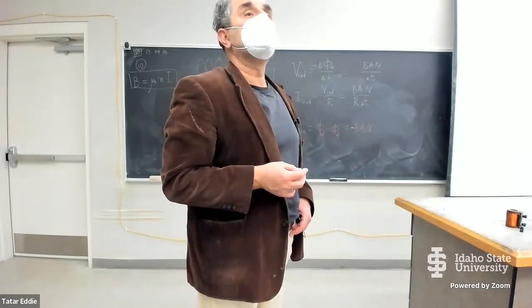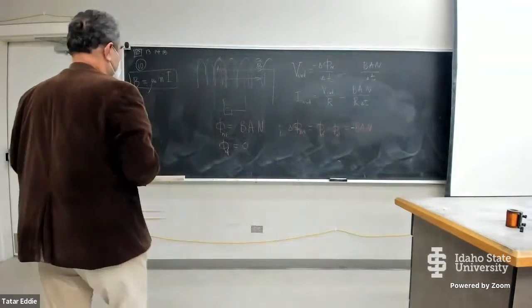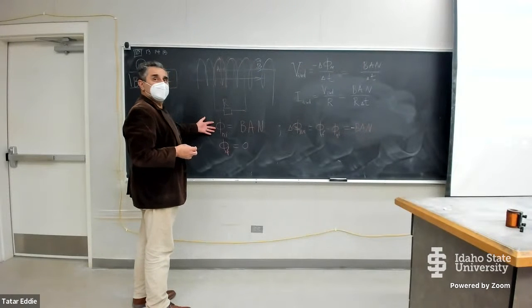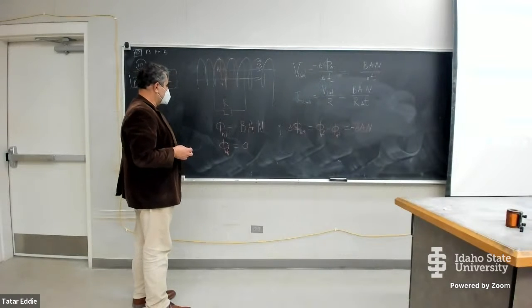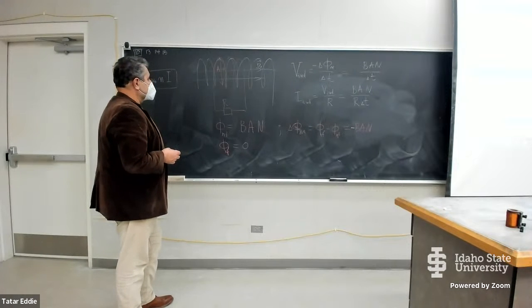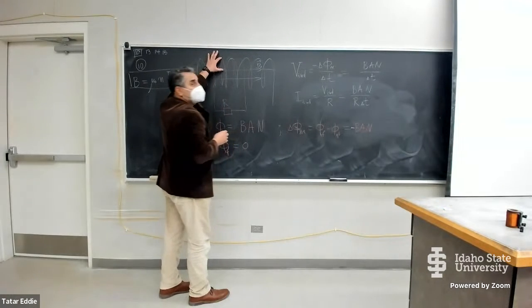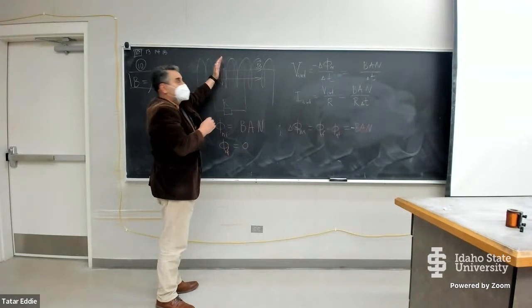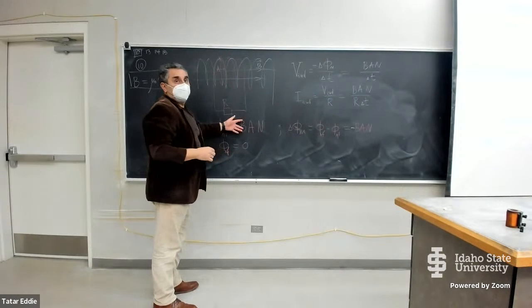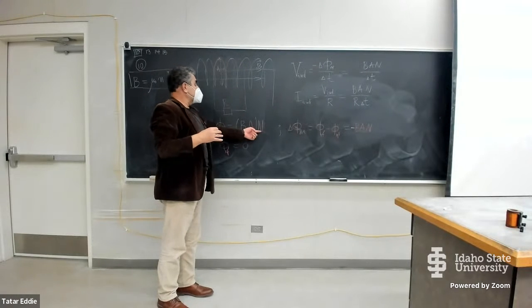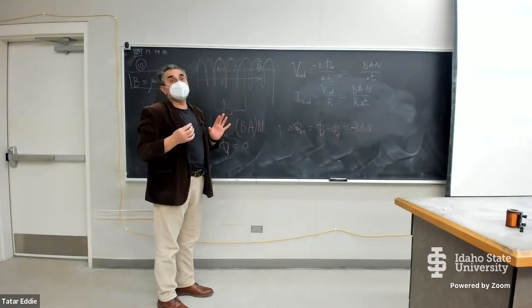Yes. One question I have is for the equation that you drew underneath the resistor. When you learned it, I thought it was N times the flux equals B times A. So when you move N to the other side, when you divide by it, I'm just confused why it is on the top. No, look, this is the total flux. So B times A is going to be the flux through one turn. B times A is the flux in one turn of the coil. 10 turns are going to have 10 times larger magnetic flux.